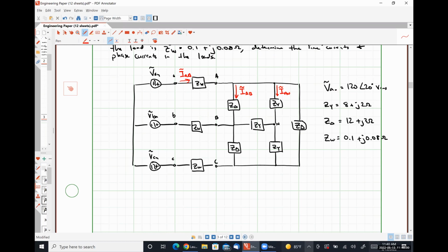Yeah, so the fact that there's a delta connected impedance is going to kind of mess things up, right? But we have a means by which to convert a delta connected impedance into a Y connected impedance. How do we do that? So for the impedances, there's no square root involved. To go from Y to delta, we multiply by 3. To go from delta to Y, we divide by a factor of 3.